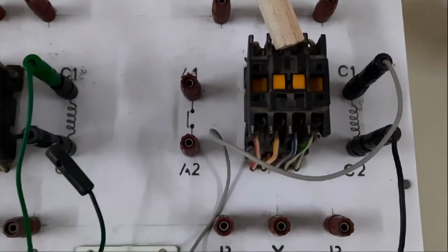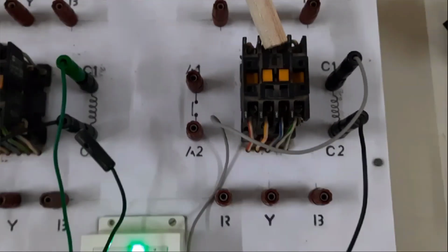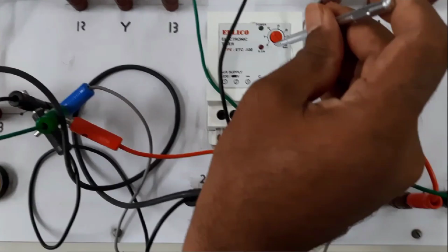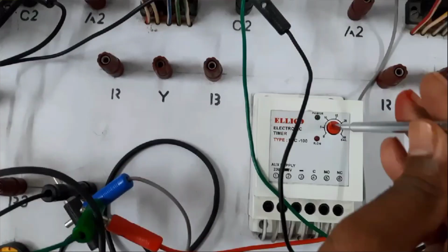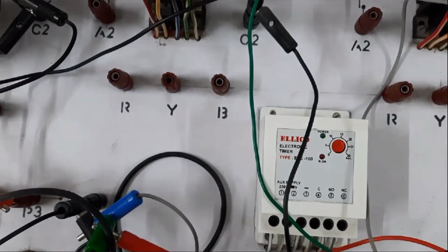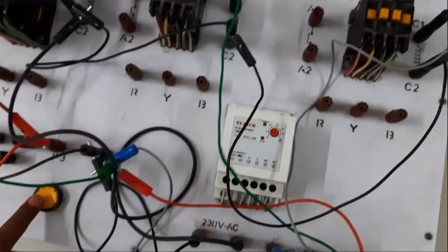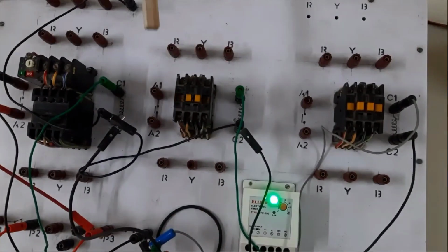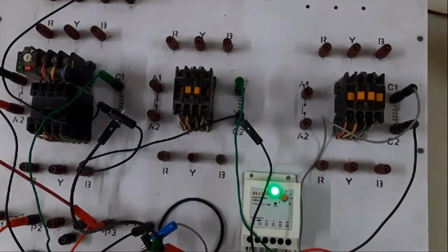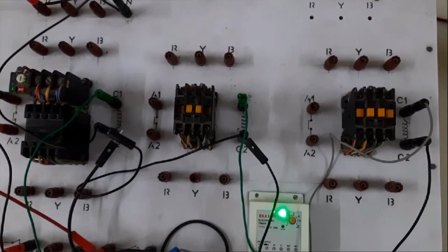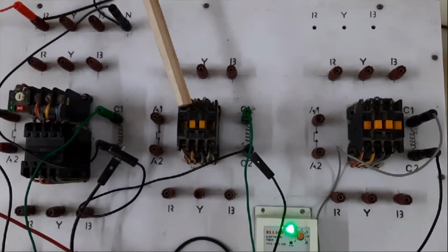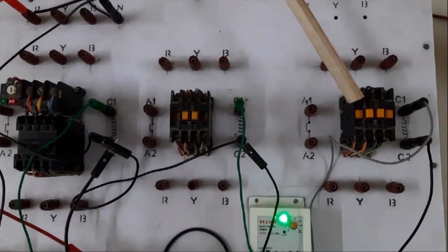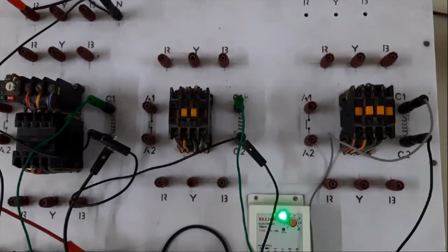We will repeat this experiment for a higher time. So let us turn off. Let us increase the time. We increase the time from 10 to 20 seconds and now we again repeat. Now observe, these two contactors will be picked up and the timing has started. Approximately after 20 to 22 seconds, this contactor will turn off and this contactor will turn on. So the motor will fall in delta connection. So let us wait for the time to get over.